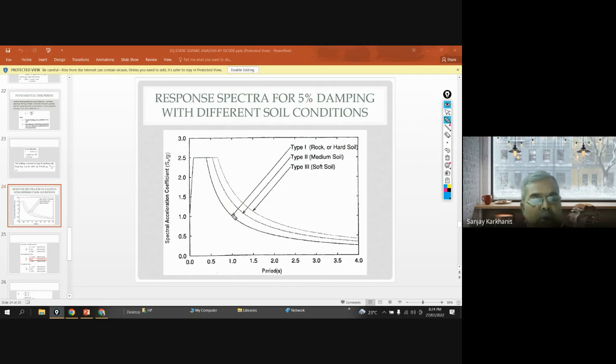So whatever you have applied for one accelerogram for various time periods, entire earthquake data is calculated, then it is summarized or made uniform so that you will have a conservative SA by G, right? Because this response spectra concept helps you to analyze your structure for future earthquake.